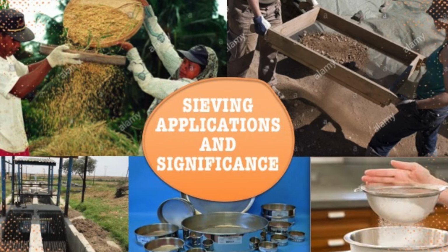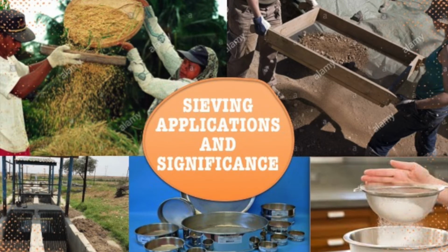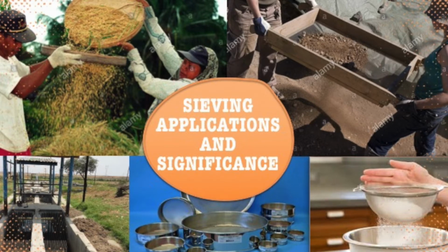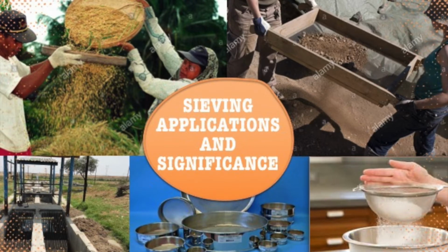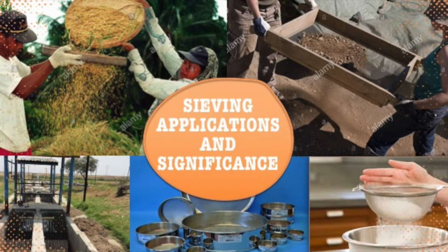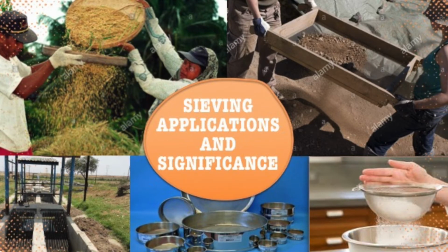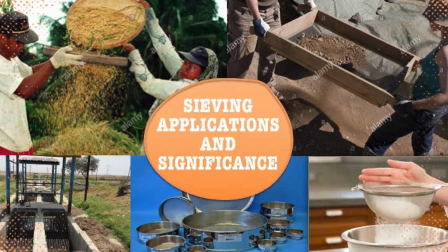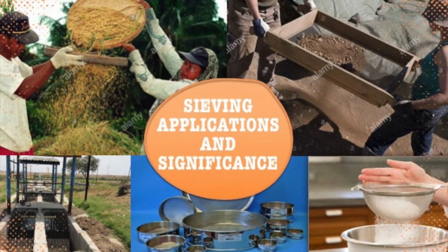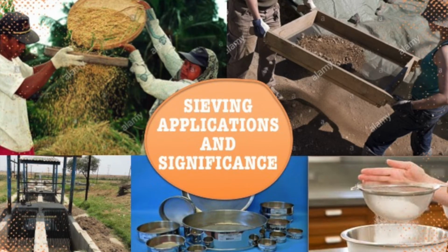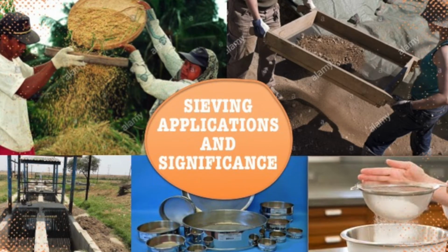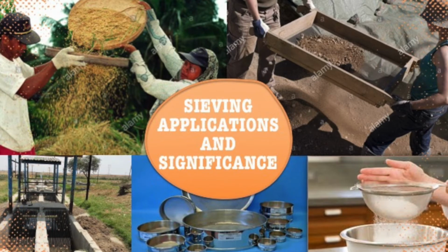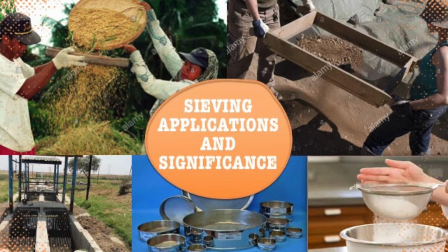On the upper left corner, you can see grain cleaned after harvest. This is important as it removes unwanted materials from the grain. Clean grain has a higher value than grain that is contaminated with smaller materials like straws, chaff, weed seeds, soil particles, and stones, rubbish, and other non-grain materials, and all of these can be removed by sieving the grain through a smaller sized screen, perhaps a 1.4 mm or less sieve opening. Sometimes cleaners are included in a thresher.